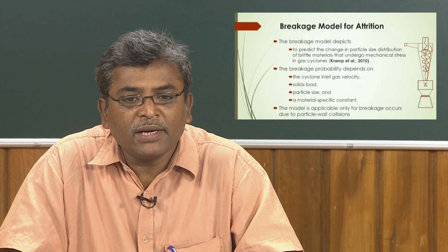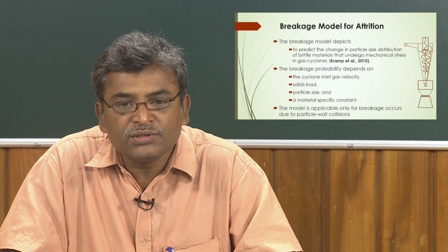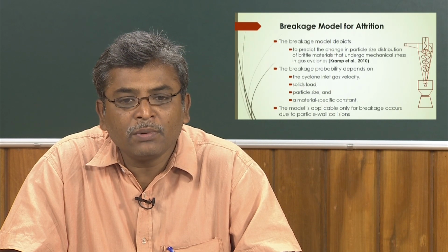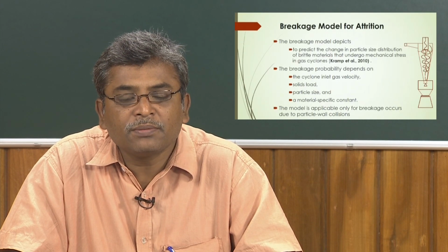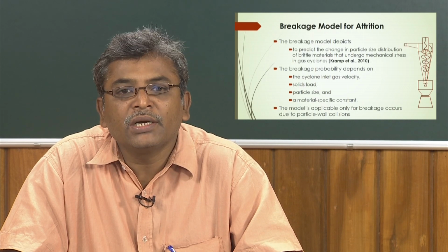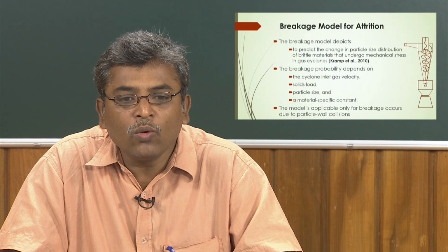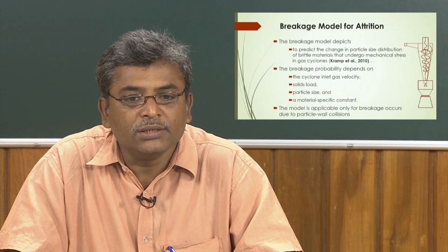The breakage efficiency depends on the breakage probability, and that breakage probability depends on the cyclone inlet gas velocity, the solids load, and the particle size.